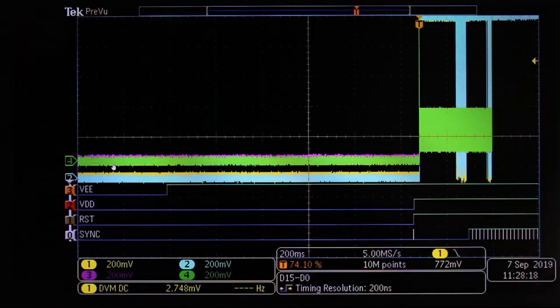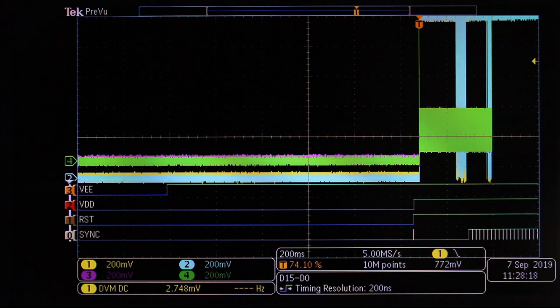Let's look at a few captures from the oscilloscope. In the shown image, iPod wakes up from the sleep, does an init, cleans the display, and then writes first frame over to the display. Here at the trigger point, iPod turns on the display. Here you can see iPod turn on the VEE voltage, and here at this triggering point issues a reset sequence and sends some commands right here, tries to clear display here, and then ultimately sends the visible frame here. You can see right after the clearing display started generating sync pulse.